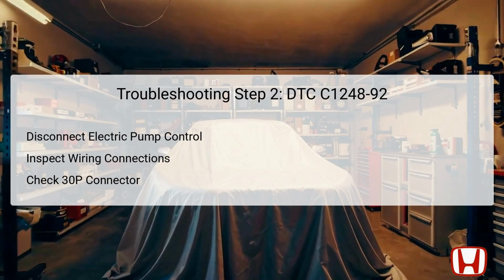It's also important to check the functional status of the electric vacuum pump itself, as any irregularities could inadvertently contribute to DTC C1248-92. Inspecting the wiring at this point is crucial, ensuring all elements are intact without any visible signs of wear